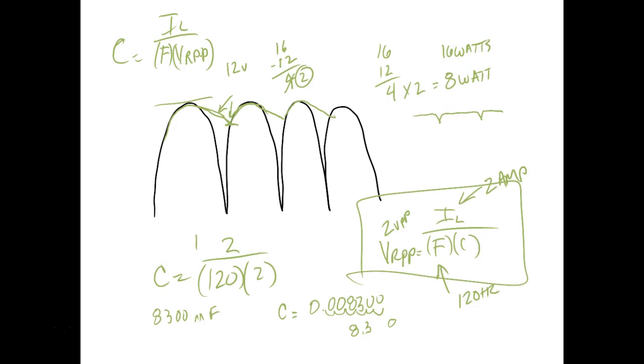So we knew it was getting 16 volts peak, and we said, okay, we're regulating 12. What's the difference between 16 and 12? That would put our value exactly at 12. But we don't want to put our value at 12 when our regulator is regulating at 12, right? So what did we do? We halved it. That gives us a 50% safety margin on our load.